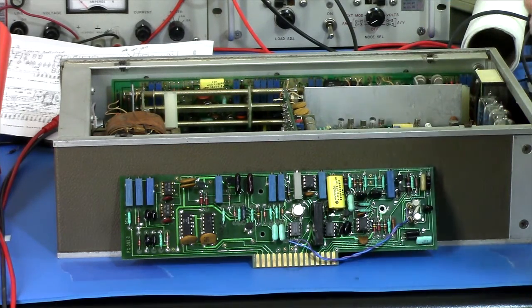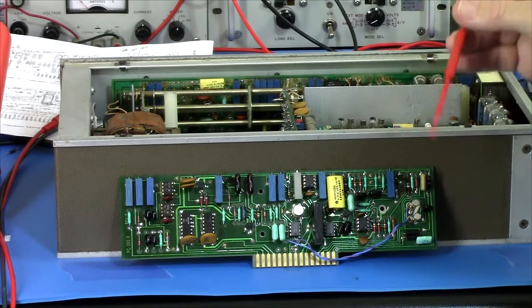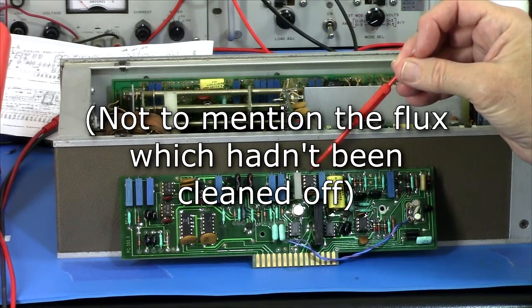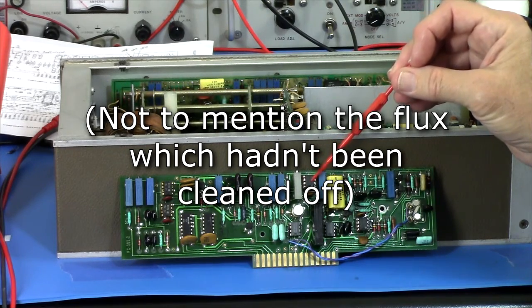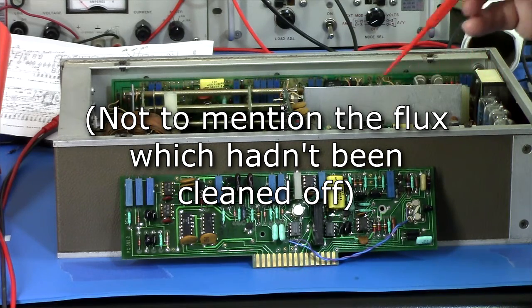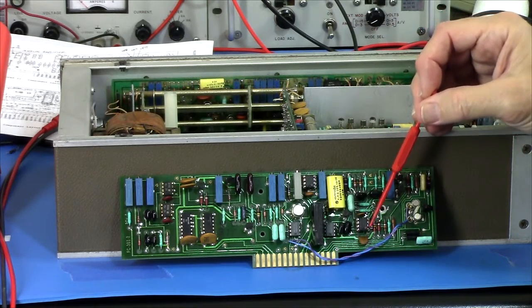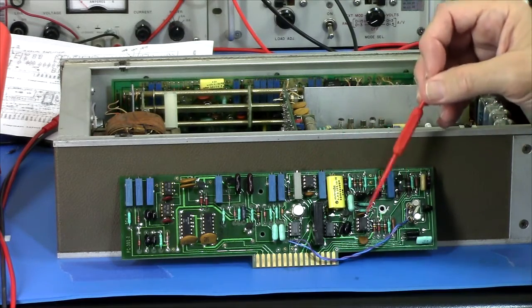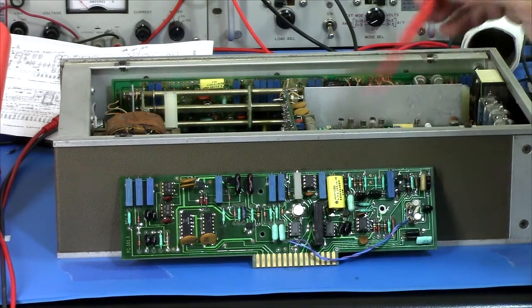And how could I tell that? Well, from the solder pads being a little shinier, and from the date codes being 1976, where everything else is like 73, 74. So I've taken those out and replaced them with sockets so that I can test with those out of circuit and also swap in different chips.